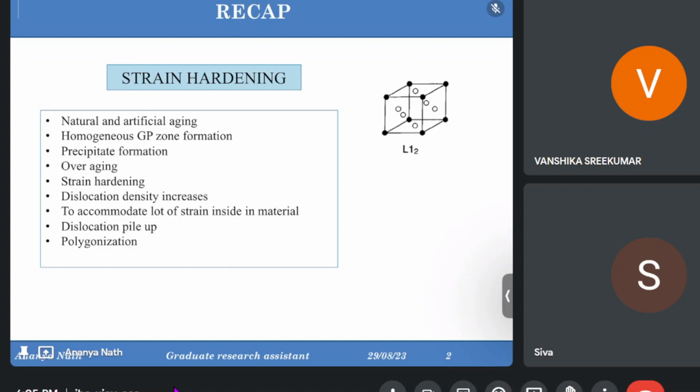Cold working comes with different processes again, like stretching, drawing, extrusion, then just normal forming or forging processes. These are basically the cold working processes. If we increase the temperature, it will be called hot working. But ideally, temperature doesn't make any difference in the non-heat treatable alloys. This is why we typically use cold working techniques to increase their hardness.